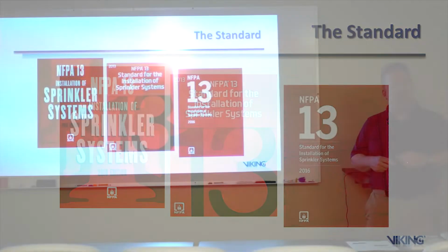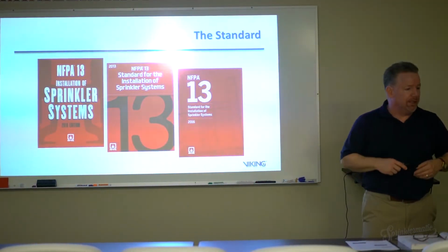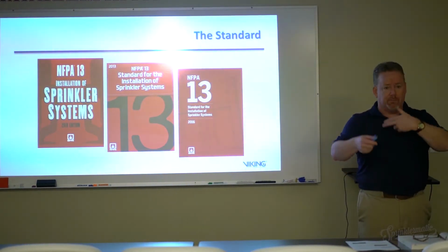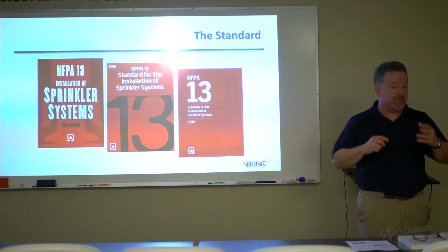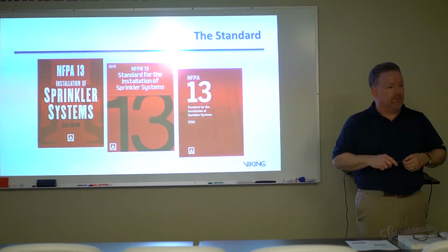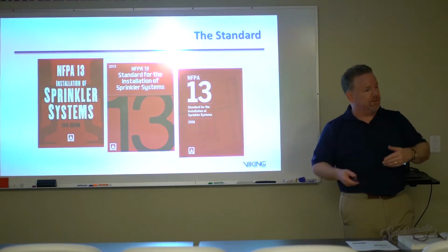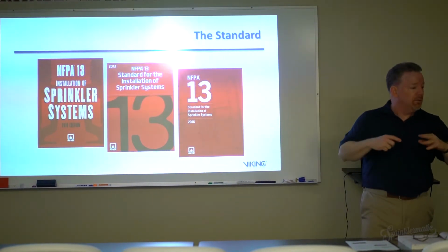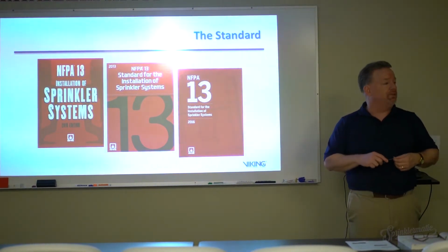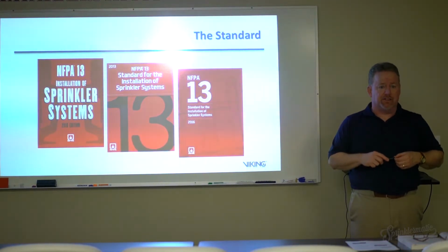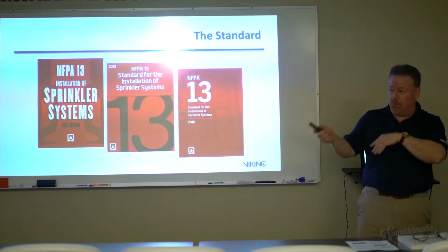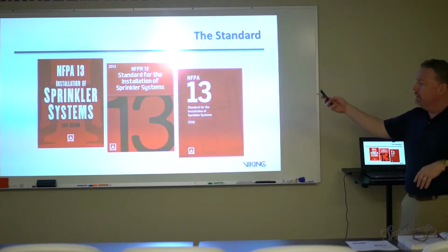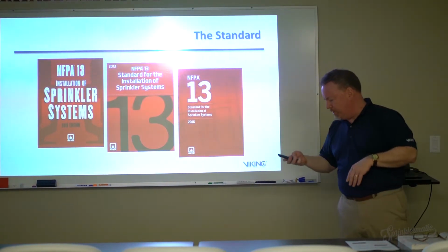It's been around for over 100 years. It's been changing every 3 years. So the requirements in NFPA 13 kind of flip around. Every now and again, you'll change some pretty significant ones. As I said in the previous session, we talked about the one in 2001 that said all light hazard occupancies will now have quick response sprinklers in them. That was a big change in the document, and since then we've been working with that rule. So just over the years, every 3 years it gets changed.